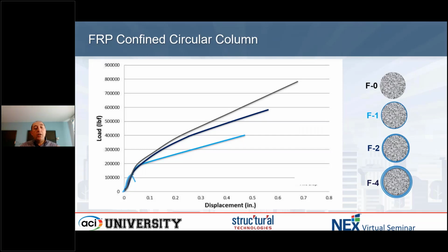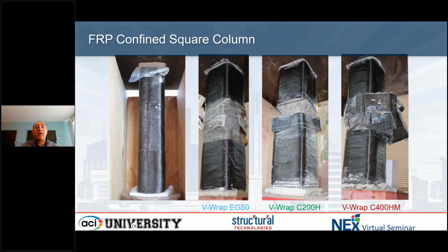I think Kent mentioned earlier, and it's also important to mention here, that what we focus on in seismic upgrade is not really the increase in capacity. Also keep in mind that there is a limit on how much we can increase capacity for gravity loading. What we focus on is ductility: you can see the brittle concrete that failed at small displacement, and now we have a lot of ductility. That is very important to be able to dissipate energy.